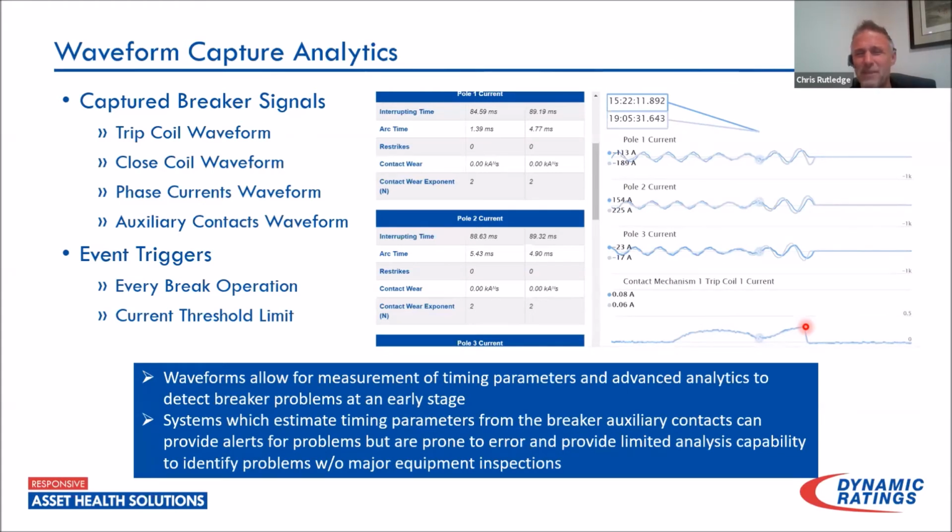So I've seen with a lot of the other breaker monitors and even relays where these times can be very misleading when based off these aux contacts, due to the aux contact possibly sticking shut. I've seen events where you'd have a breaker that would open within 30 milliseconds, but the aux contact would stick, therefore looking like the breaker did not actually open for 800 milliseconds. And you really need to catch those early, because that is going to burn your trip coil up pretty quickly if you're leaving it energized for every event.